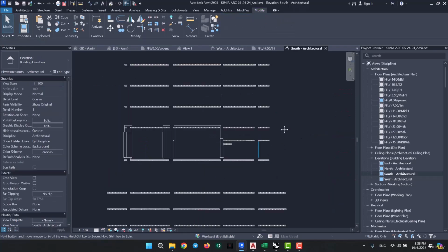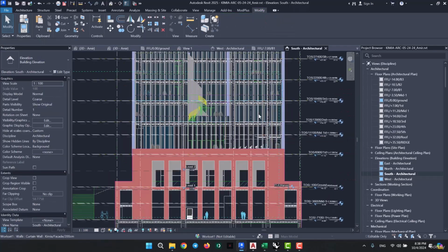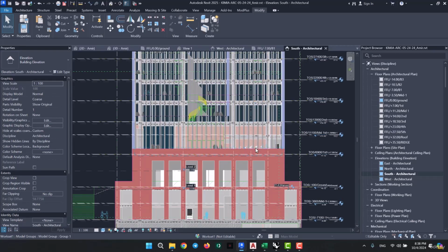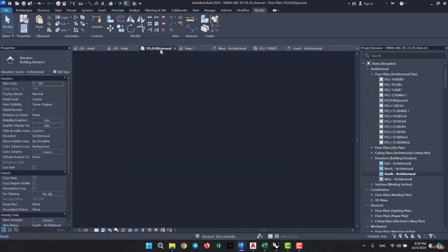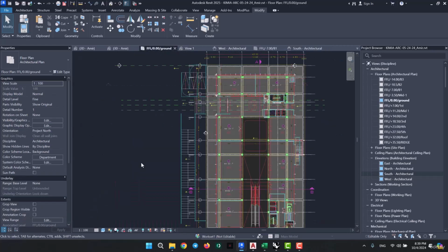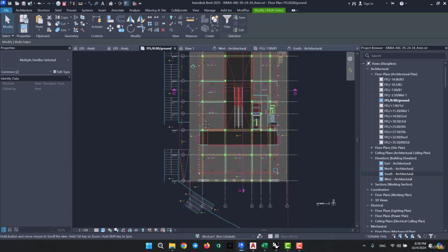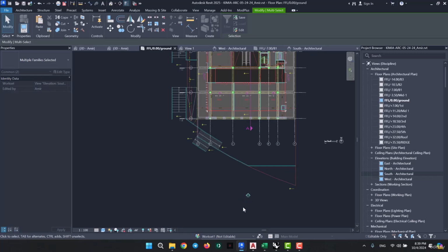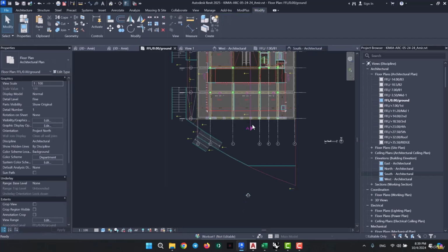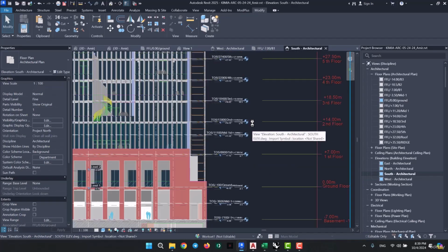Very well. Now the thing is that, do you notice how unwell our plans look? Our area looks a little too cluttered, and even when it's displayed and shaded, we can see elements that we shouldn't. Now when this happens, you might become skeptical of your elevation symbol. For instance, my elevation symbol is over here, which I'm going to have to move down and bring here. And now if I open the south elevation, our view should look less cluttered, because when that symbol was over there, we were viewing elements from the middle of the plan.